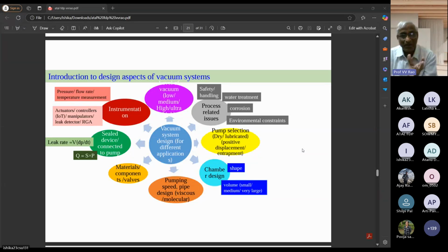But from the chemistry point of view, you still have 10 molecules of oxygen or hydrogen. That fellow may be having 100 molecules, but all 100 are inert gas. So nothing will happen to the semiconductor. They will not get doped. So that is called our residual gas analysis. It's not only important to get a good vacuum, you should analyze the residual, whatever is the residue. Okay, that is very important.